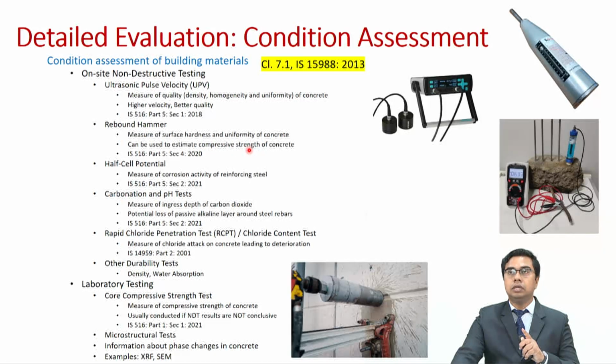So, it is important that you use the same chart provided by the manufacturer on the same equipment. You do not use the chart provided on a different equipment. So, here we have a rebound hammer, as you can see the rebound number can be read from this very scale, and there is a chart provided over here which gives you estimate of the compressive strength of concrete. This is your ultrasonic pulse velocity meter, which we have already discussed.